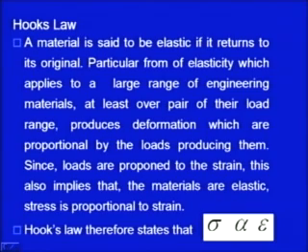Always they are proportional to the load application: how much load you apply, the corresponding elastic deformation is there in the object. Since the loads are proportional to the strain, this also implies that the material is elastic. Because the load application is there, the internal resistive forces are there, the stress is there. So we can say the stress is proportional to strain, or the intensity of resistive forces is proportional to the corresponding deformation, because the strain is the measure of deformation.